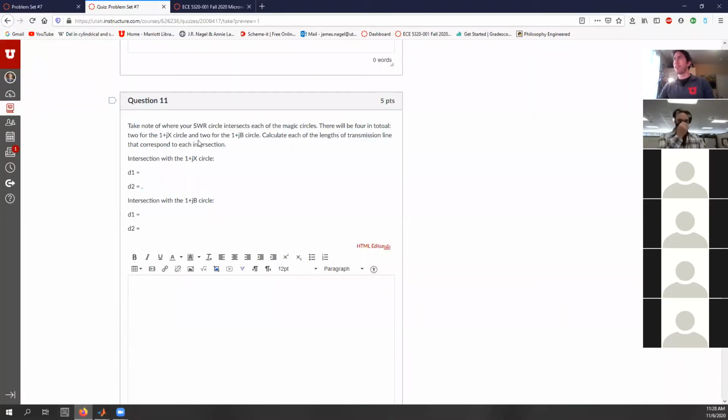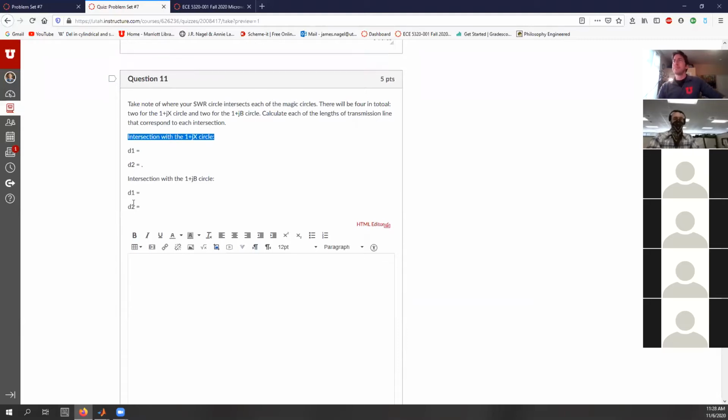So that's sort of what I'm going for with these, so that you have that picture of your paths that are allowed. And so there's a lot of overlap between this and the lab. And the only new thing here that isn't in the lab is the 1 plus jX for the series stub. But I don't feel like it's worth testing you on that. It's worth doing once just to see it, but again, I'd be very surprised to see an application that used a series stub rather than the shunt. Maybe someone out there has done it. It just feels like most of the time, especially in the university setting, microstrip is the nice cheap stuff that we can do everything with. So it makes the most sense to focus on that case.